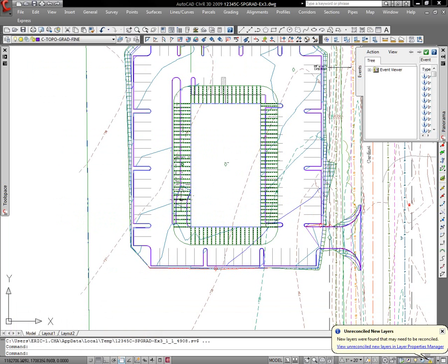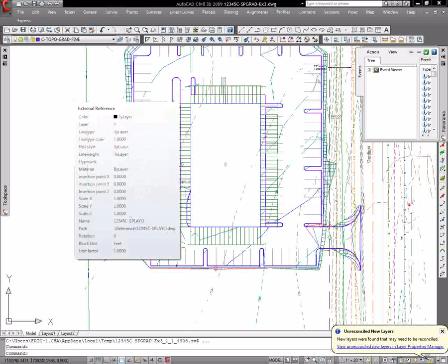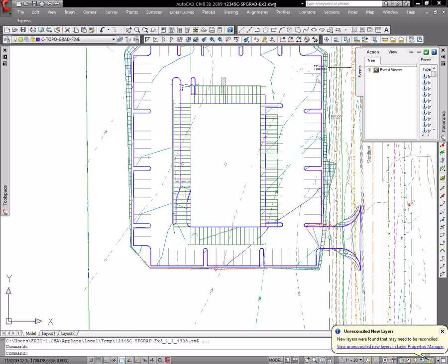The change in the contours here shows a steeper slope along this portion of the drive-through road, and that's exactly what we'd expect to see because we just flattened this part out, which would in turn make this part steeper. We've also flattened out the area in front of the building, which is going to make this area steeper as well. So everything happened exactly as we wanted.